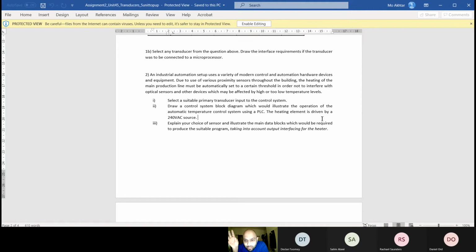And then also, when that emergency stop's been activated, a signal from the output of that stop goes back into the input of the PLC, and on the HMI you can say emergency stop's been activated. Does that make sense? So you've got some kind of feedback. You're telling the PLC this has been activated, not to get permission, but to tell it, so you would know whether to continue with an operation or not.